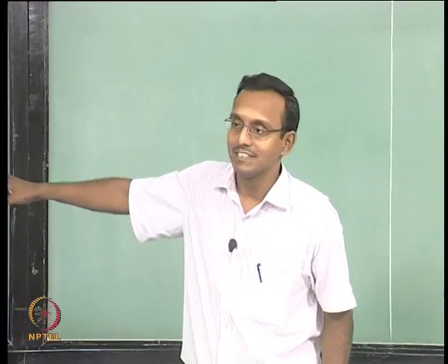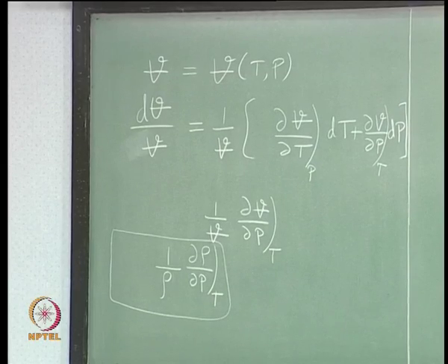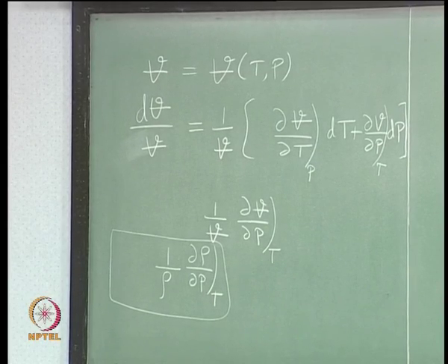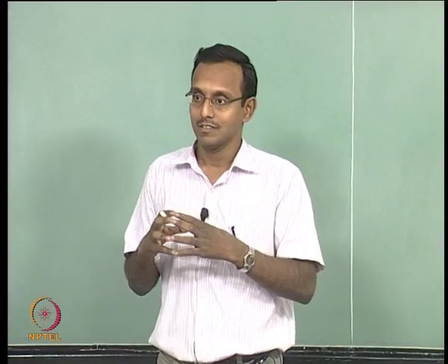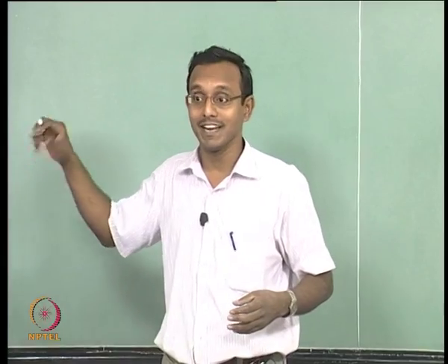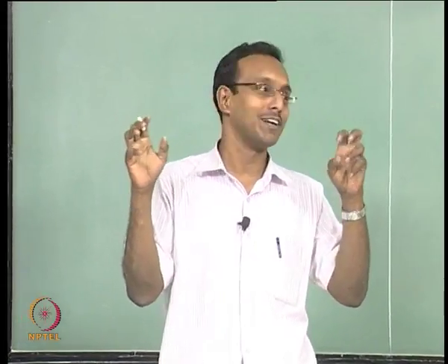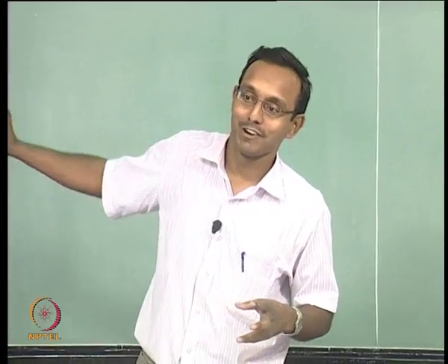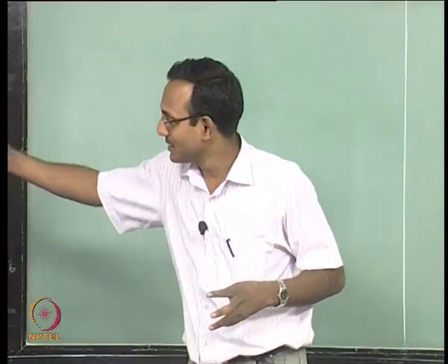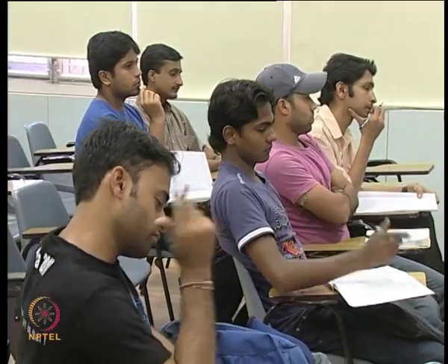If we are looking at the density based term, but if you are looking at specific volume term, then if pressure increases, typically volume decreases at constant temperature. So, dV by dP will be negative, but we want to call bulk modulus a positive quantity, right. So, if that is the case, then we will put a negative sign in front of it. But if we are using density, it should not affect at all. We will keep it the same.